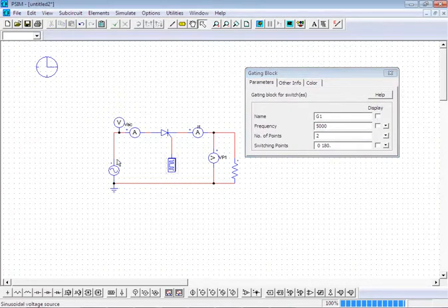Now since it's a thyristor, I'm not having this gating signal with the MOSFET, so this should work with the line frequency. So let us first convert this into a 60 Hertz signal, and then we have number of points 2. I just need to turn it on. If I turn on the switch for a small interval of time, it will stay on as long as we have a positive half cycle on the anode of this thyristor. This means that we are not forcing it to commute. It will naturally commute. So a very small pulse is required.